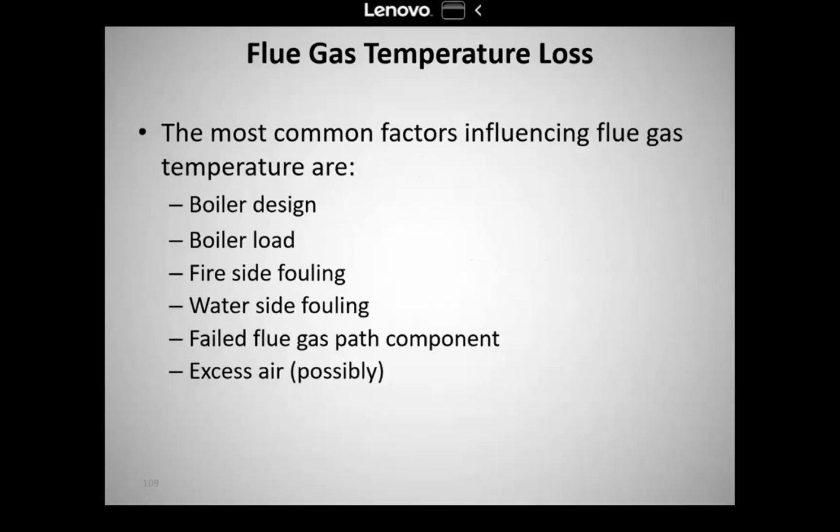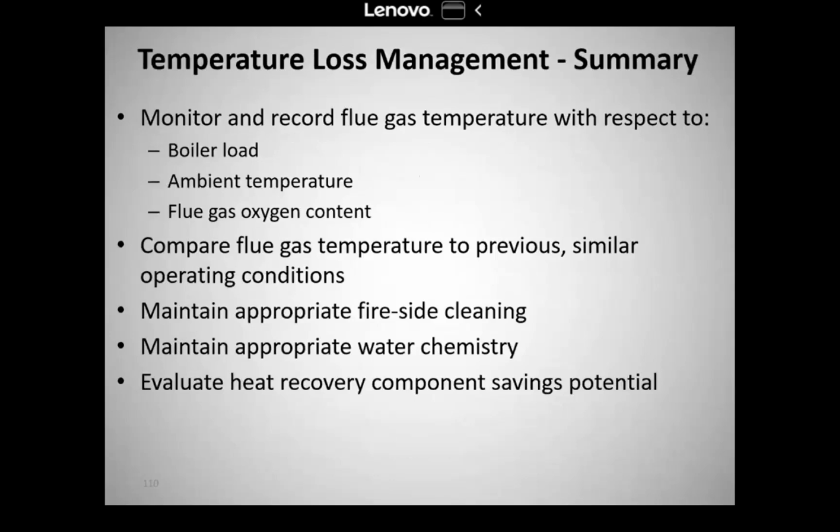Okay, the most common factors influencing flue gas temperature, and this just summarizes what we've been through. So I'm not going to read back through those for you again. Okay, so the temperature loss management summary. So this is what we need to consider. Monitor and record flue gas temperature with respect to boiler load, ambient temperature, and flue gas oxygen content. Okay, we'll get into that.